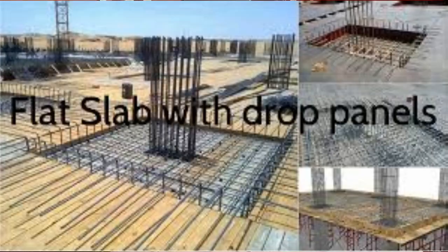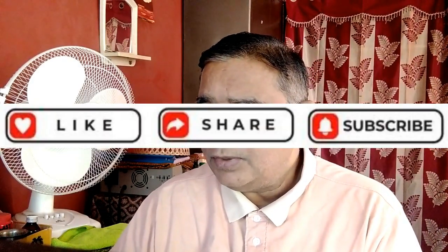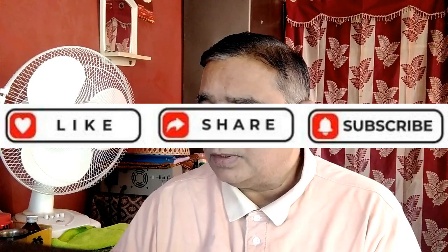And next point is, what is the advantage of flat plate slab? Advantages of a flat plate floor system. The flat plate floor system requires a simple formwork. The system is suitable for a direct fix or sprayed ceiling. The structural depth of a flat plate floor is minimum. Reduced depth of a slab helps to increase the floor height of the building.